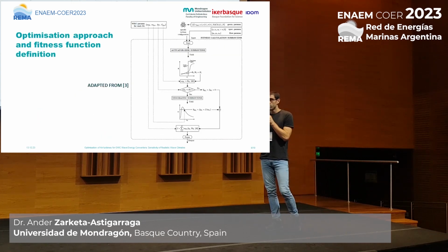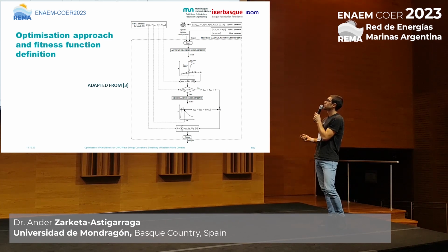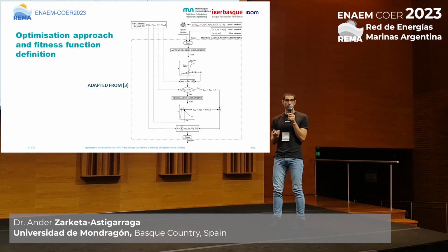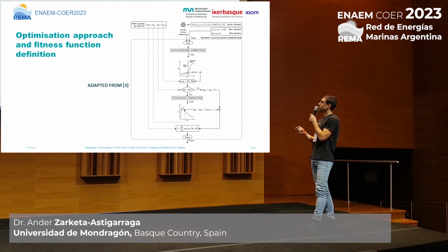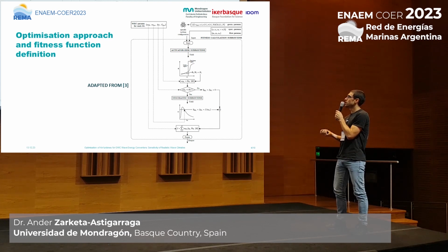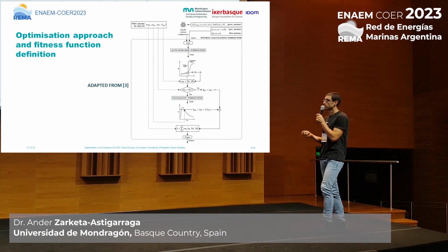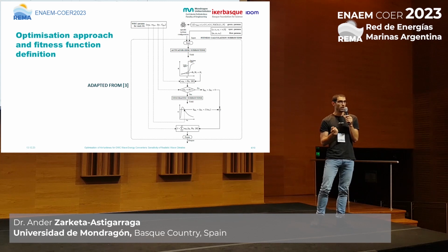So with all that information, we can describe the optimization strategy we are carrying out. We start by introducing some turbine configuration, and we compute the steady state curves for a given C state. Now we focus our attention on the phi-psi curve, as shown here, that we know is a linear relationship between phi and psi for pure stall conditions. Okay? So this is linear, we calculate the slope k.